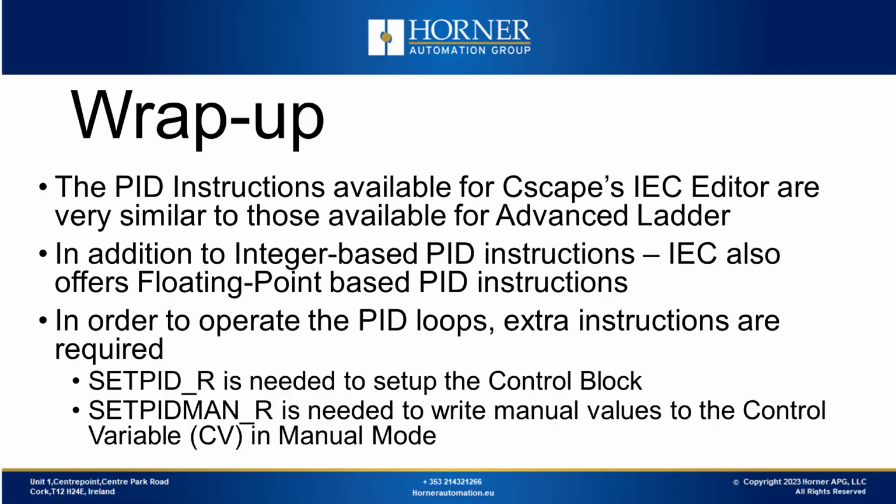So as we saw today, the PID instructions available for Cscape's IEC Editor are very like those available for Advanced Ladder. In addition to integer-based PID instructions, IEC also offers floating point-based PID instructions. It is important to keep in mind that in order to operate the PID loops, there will be a couple of other instructions to be aware of, one to manipulate and set up the control block, and another for the writing of manual values to the control variable.